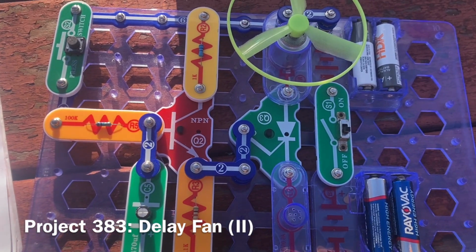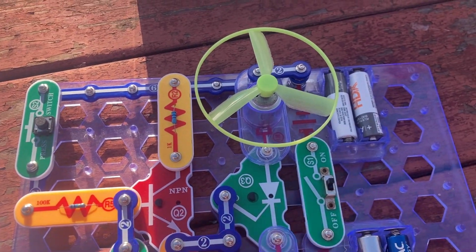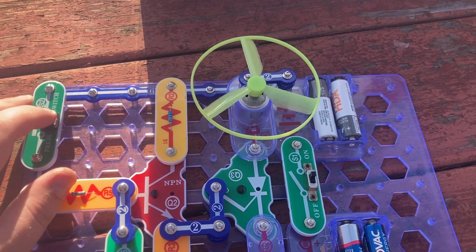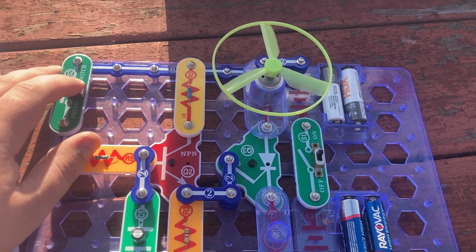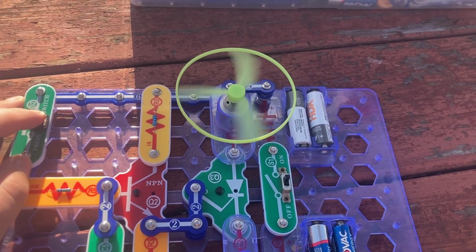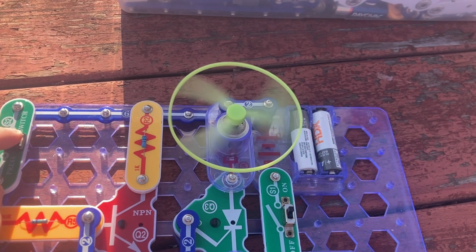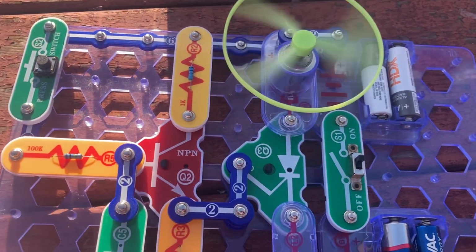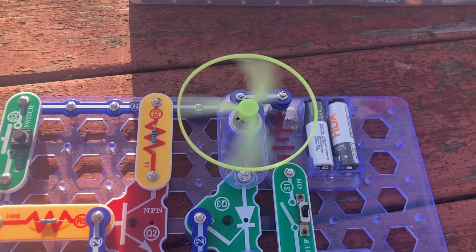For the variant of the delay fan, I replaced the C4 capacitor with the C5 one. Now let's see how long it takes for the fan to turn on after I hold down the press switch. It takes significantly longer for it to come on compared to when I was using the C4 capacitor. The greater the capacitance, the longer the delay for the fan or whatever to turn on.